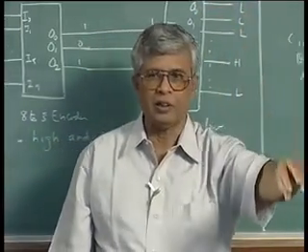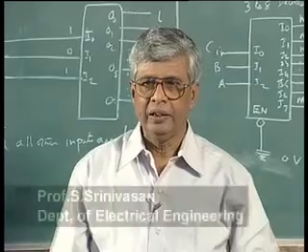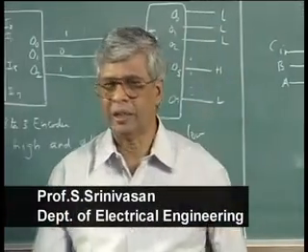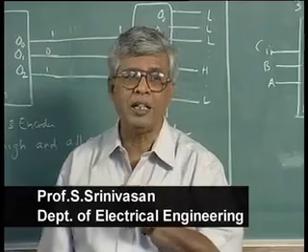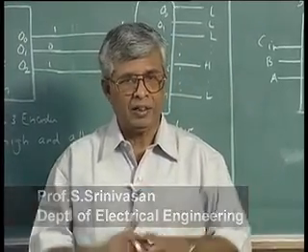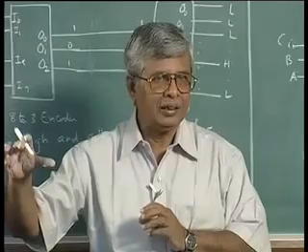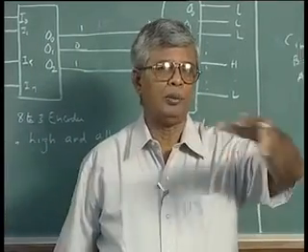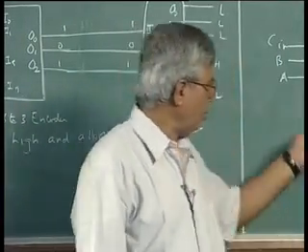Physically you may have inserted the IC in a socket, but electrically it is not there. Electrically you can ignore it. Such things are required very much because many designs are complex designs where several ICs have to coexist, and certain operations require certain paths. At that time the other circuit should not come in the way. How do you control it? By these enable signals. And there may be more than one enable.